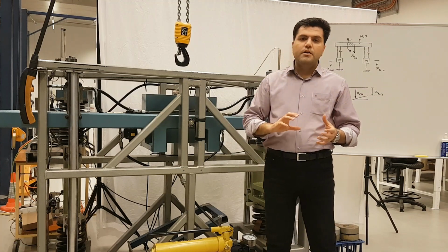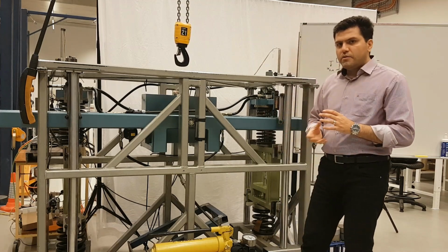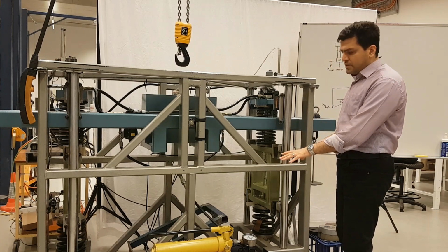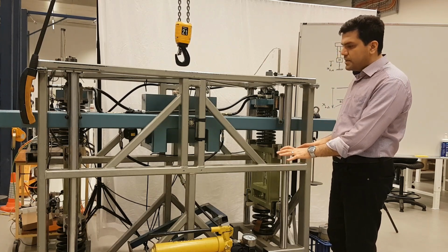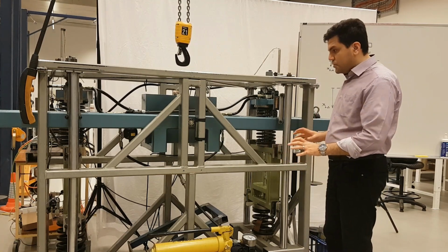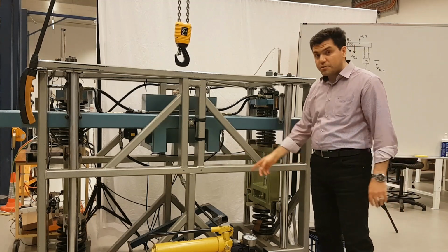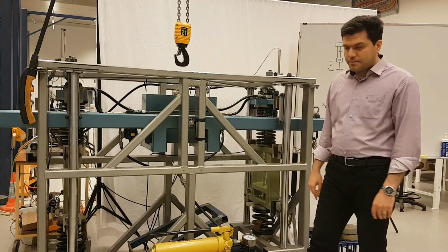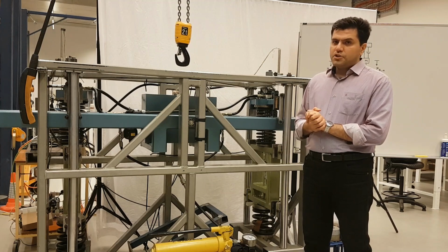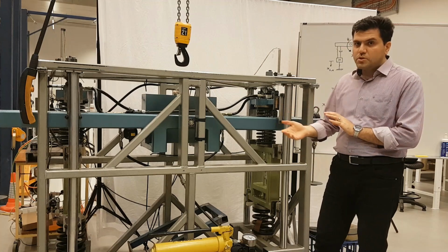You know that the stiffness of the tires could be changed by changing the inflation and other parameters, such as the material of the tires. But here we assume the stiffness of the tires is fixed, and there is no damping because we don't have any damper for these 2 green masses. What we're interested in this test is to identify the natural frequencies of the system and the damping ratios for different modes of vibration.